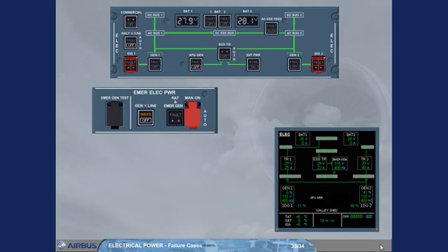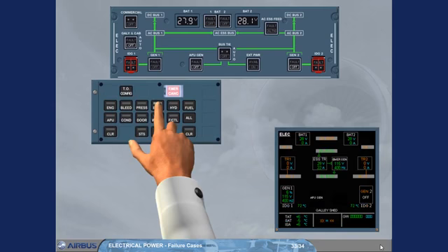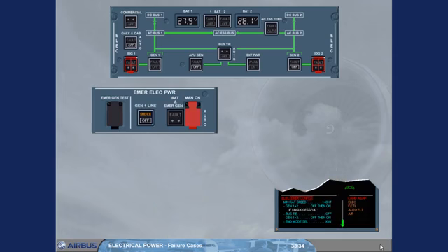As soon as the GEN 2 push-button switch is set to off, the emergency electrical configuration is set, as shown on the engine warning display, and also on the ECAM ELEC page, when it is maintained displayed on the engine warning display. So, we will stop here, as you should continue to apply the QRH to know which part of the ECAM has to be followed.